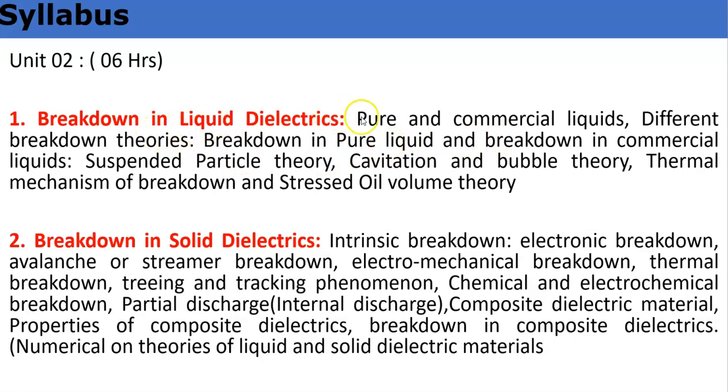So breakdown in liquid dielectrics: pure and commercial liquids we have to see. Then different breakdown theories: how breakdown will occur in pure liquid, and how breakdown will occur in commercial liquids. In commercial liquids, we have to see four theories: suspended particle theory, cavitation and bubble theory, thermal mechanism of breakdown, and stressed oil theory. Generally, I am observing students get confused. There should not be confusion. You have to keep a clear picture of the theory.